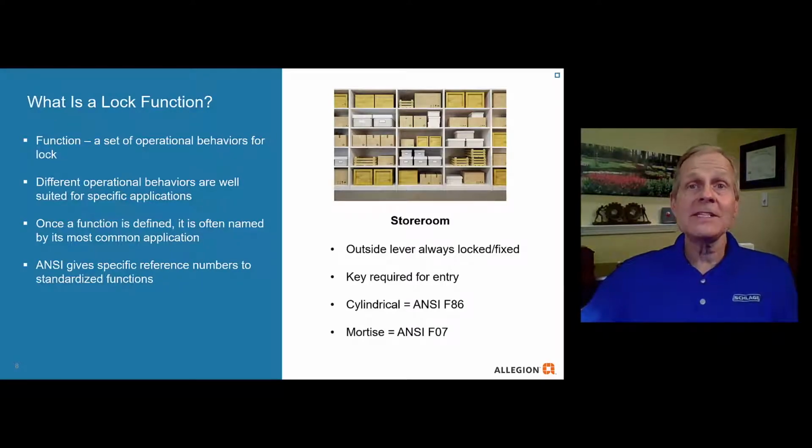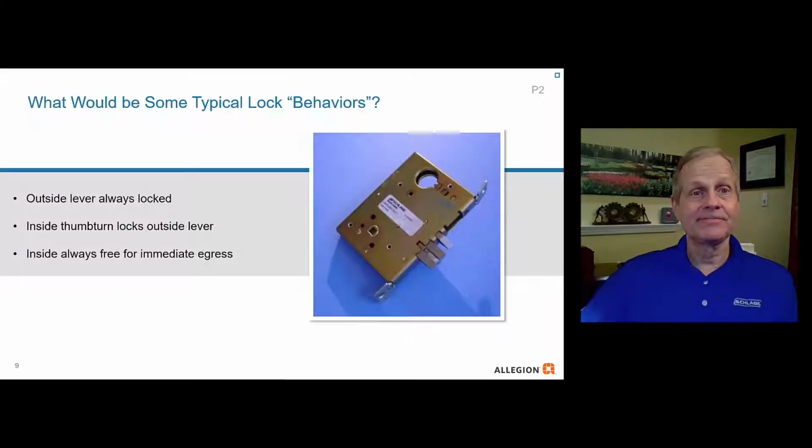So if you are replacing one model or brand of lock with another brand, and you find the same ANSI number in both manufacturers' catalogs, you know that the function will work the same way. Mounting holes should be similar, but especially in a mortise lock, they're generally going to be different. Some of the mounting holes for the cylinder, the through mounting bolts, the spindles, are going to be different. There are no standards for those dimensions. Cylindrical locks are a little more universal. Generally, the only thing that changes is the position of the through mounting bolts on a cylindrical lock set.